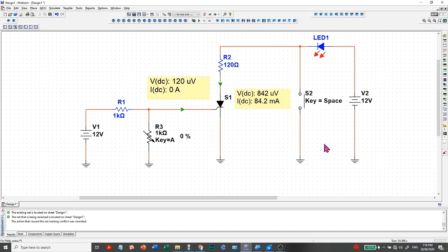Okay, let's try this one. I hope it works. I have not tried it earlier. So yeah, let's go. And right now we are turned off. The LED is turned off because this is the start of our simulation, and we have not supplied a trigger voltage. So when we trigger it to more than the 2.5 volts trigger voltage, the LED will turn on. And again, the behavior is once turned on, it will not turn off.